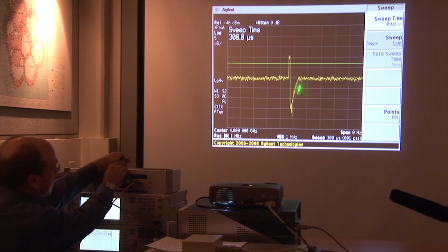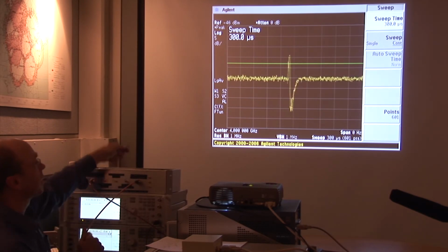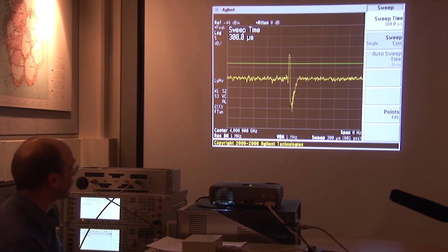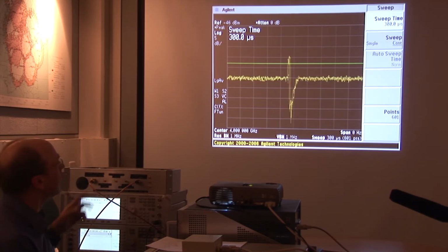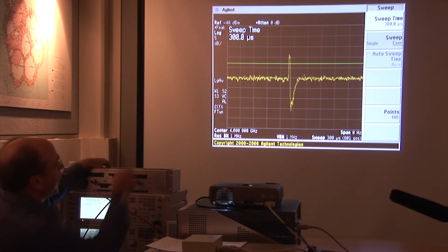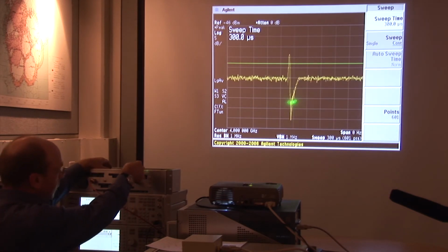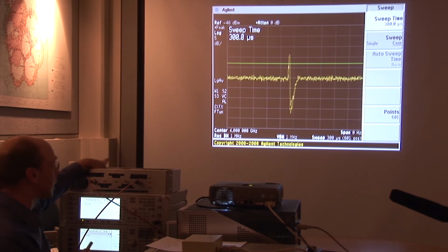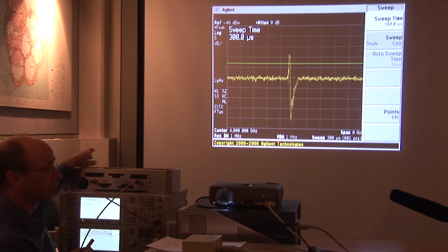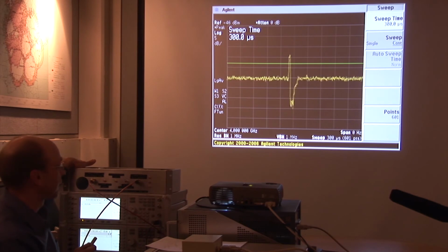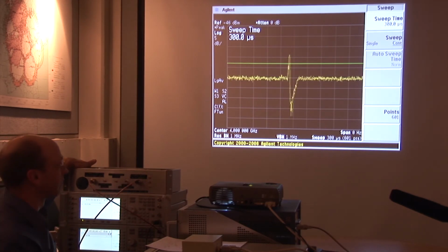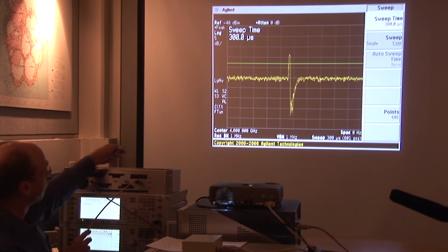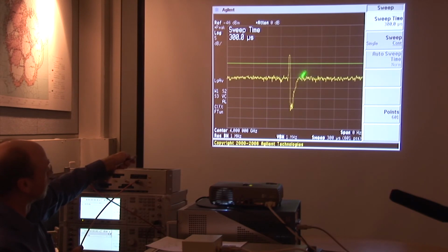So this system is losing all that data right in there. And depending upon the system, it can cause an effect that ranges, if it's an analog system, as I said, anywhere from speckles on a TV screen or a buzz if it's audio, to, if it's a digital system, an elevated bit error rate every time one of these pulses happens, to ultimately a problem with tiling or frame loss if it's something like a digital television broadcast service. And of course this would happen every 5 or 10 or 20 seconds when the radar comes around and looks at it. And if we see that happening, that's front-end overload right there.